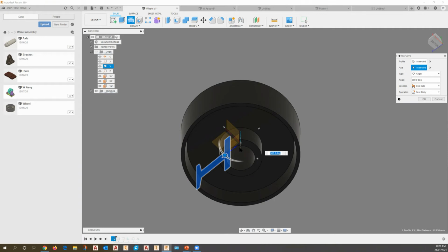Now, in most CAD systems, especially anything 3D, we work with what we call a Cartesian coordinate system, where we have X, Y, and Z axes, which is what these little icons here are representative of. So I've effectively revolved this I shape, you might call it. It's a bit like a capital I, I guess. And I've revolved it around the Y axis using the revolve command. So basically that would be one way of creating our wheel. We could simply draw the sketch of the profile or the cross section, if you like, and revolve that around any one of the axes as we'd like there.